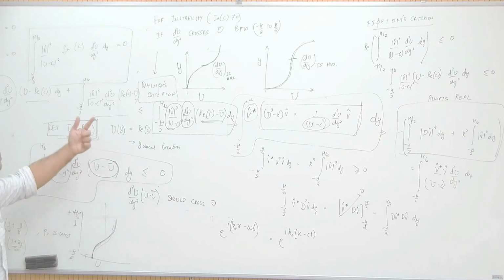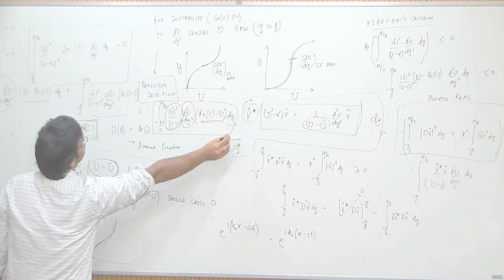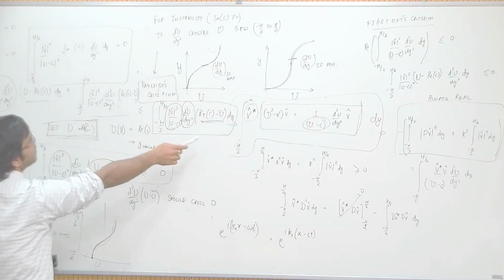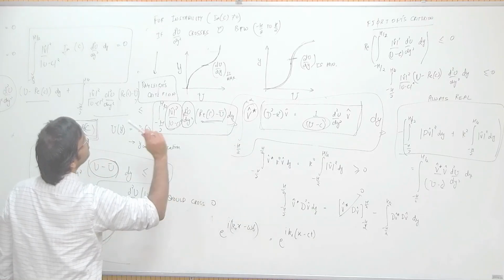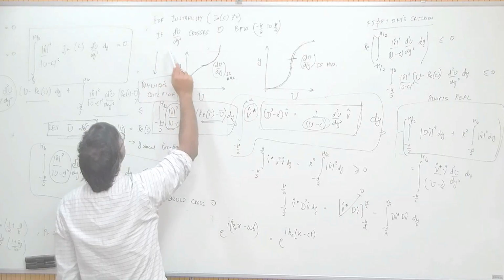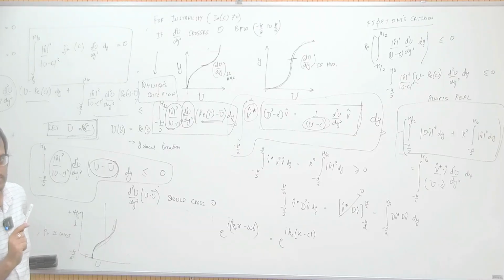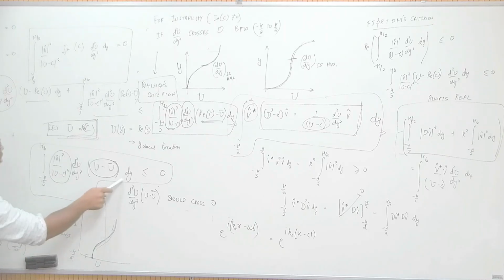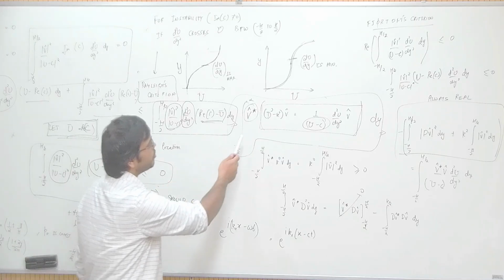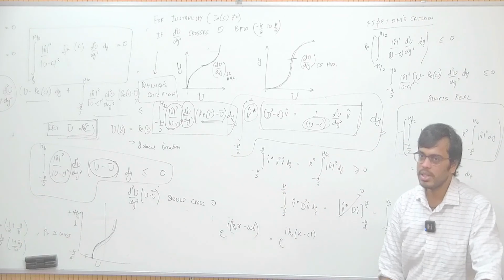Okay, now we have obtained some... So this criterion, for example, is necessary for this equation to be satisfied. The Rayleigh's equation that we have derived, it's necessary for the condition to be satisfied, for this equation to be satisfied. Now after that we said, hey, the instability requires this to be non-zero, so that means for an unstable case this should happen. Okay, we said that for instability after that. Here we did not comment anything about the imaginary part of C. So technically this equation is not really a criterion for instability. This equation is a criterion for this equation to be satisfied. We did not take anything about the imaginary part of C.